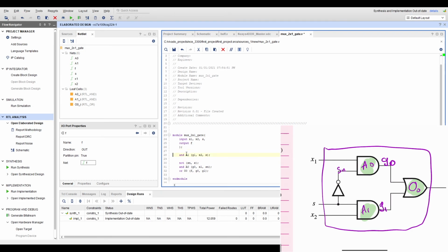As it turns out, in Verilog, in this particular situation when we're talking about structure, the order of these instructions doesn't really matter because I'm describing hardware. They're actually running concurrently, and that's what makes Verilog sometimes confusing to beginners. The order of these instructions does not matter, at least in this particular context. There are certain situations where it does, but for now, you're describing hardware. You know that X1 and X2 are all happening at the same time. This gate and this gate are all running at the same time. So it doesn't matter which one comes first in terms of code.